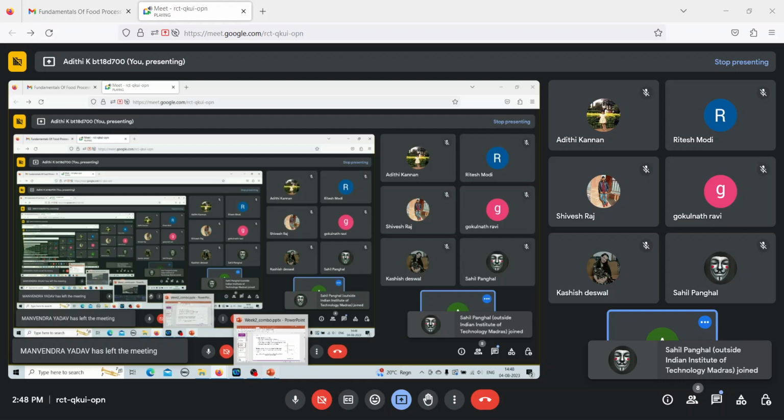In that case, what does it mean? If your relaxation time is very less than the time of observation, then it means that the fluid appears to be more viscous. Only elastic materials have very high relaxation rates. Only viscous material have low relaxation rates. So since relaxation rates of viscous fluid is very less, Deborah's number is also less and hence fluid appears to be more viscous.